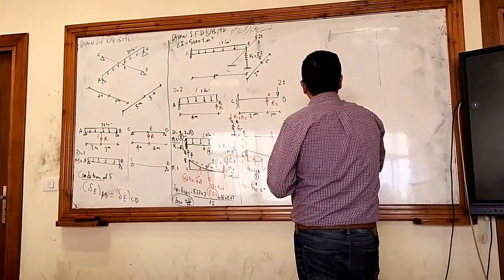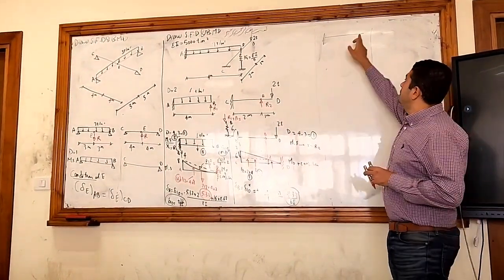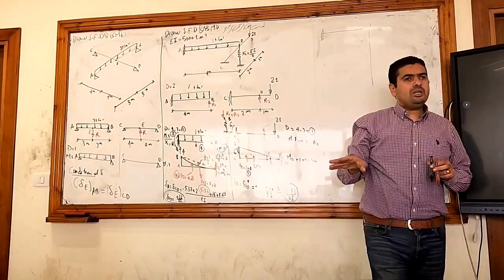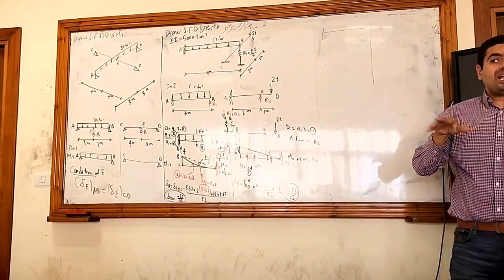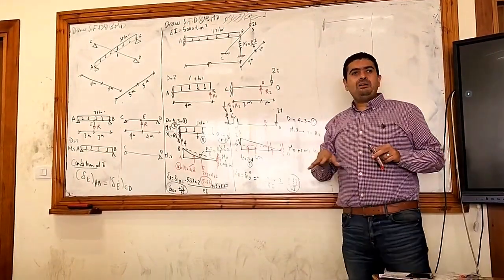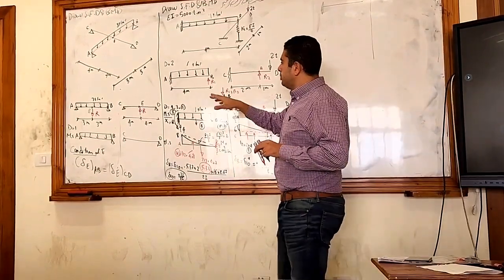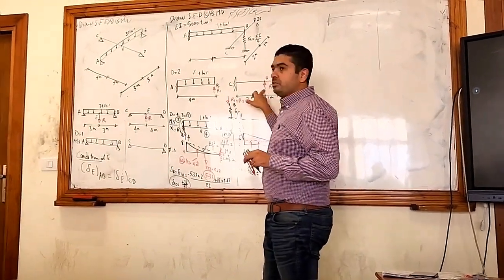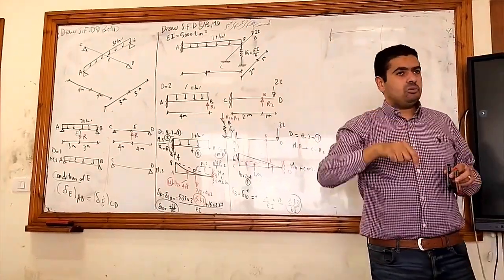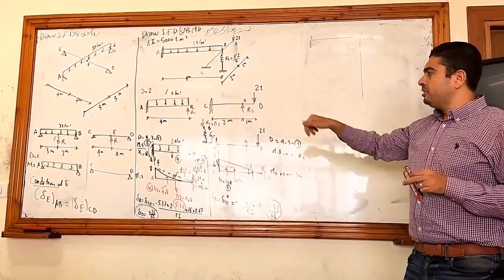And at point B, do I have the option to put the unit load of the R1 I removed on any side, on any direction? No, I chose the direction here. It's upwards. Usually do this direction upwards and let the direction on the spring be downwards. Okay, this is the regular reaction for the spring to be downwards.